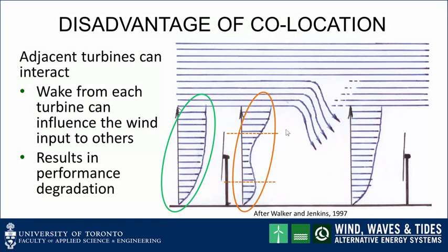Downstream of the wind turbine, faster moving air from above, or the sides if we were looking down from the top, starts to mix into the slower moving region as shown. At a considerable distance downstream, the second green circle shows that the wind speed profile in front of the second wind turbine has nearly attained the original upstream profile.